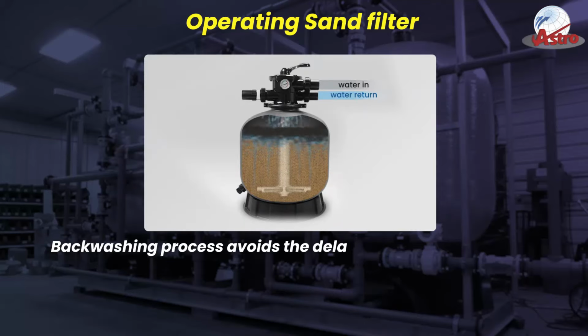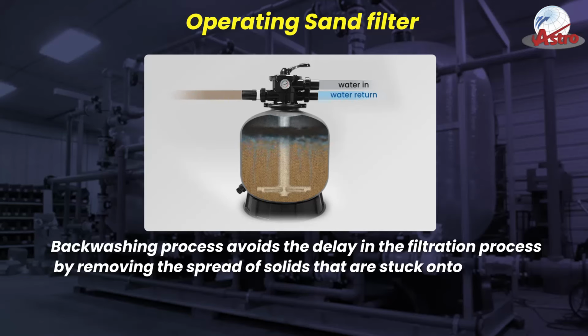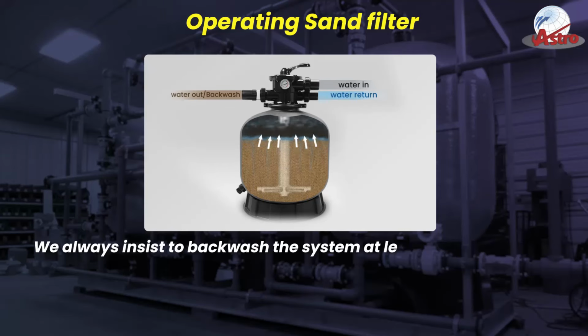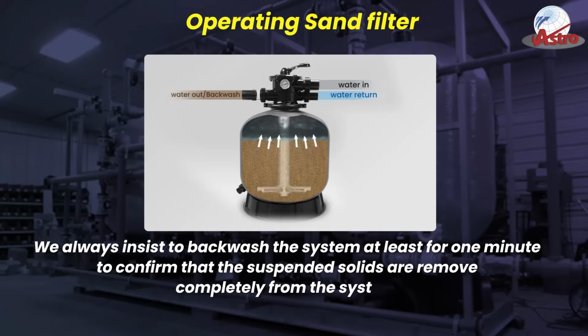Backwashing process avoids the delay in the filtration process by removing the spread of solids that are stuck onto the sand. We always insist to backwash the system at least for 1 minute to confirm that the suspended solids are removed completely from the system.